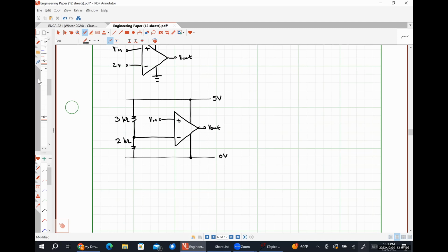because, let's see, the VX was 0. Anyway, if you're going to do the source transformation, make sure you're very meticulous about making sure that the voltage VX is defined between the same pair of nodes as it was defined originally. Because this would give you a 30 voltage source, but because VX had positive over here, I originally wrote just this combination, the positive would be over here, but because VX was sitting inside, swapped it. So now, changed the sign.